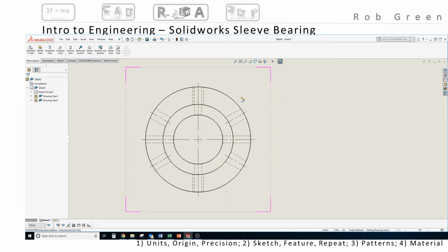And it's a spline, so it's not individual line segments, so I don't get that really nice clean line break. But I'm going to do the best I can here and include this area of the part to break out. And Solidworks is going to ask me, how deep do I want to break it out?